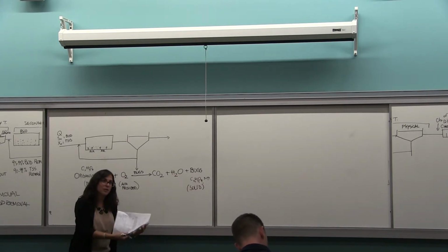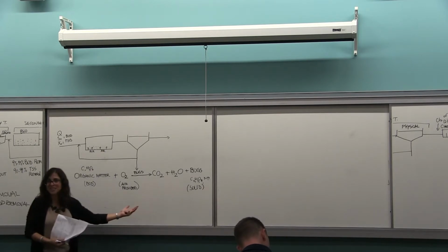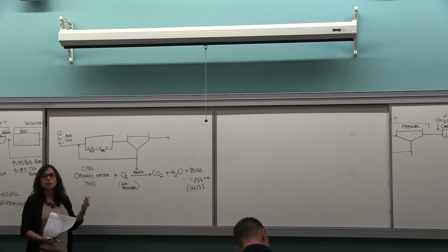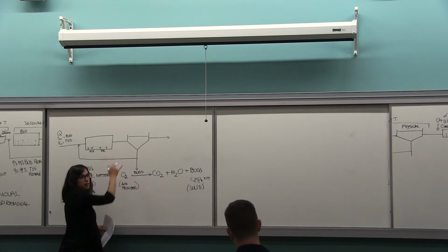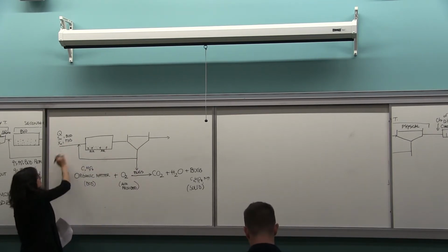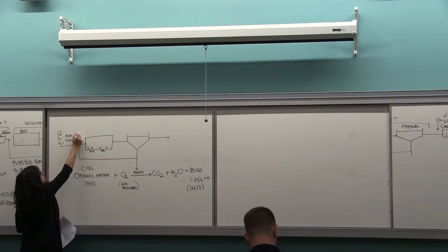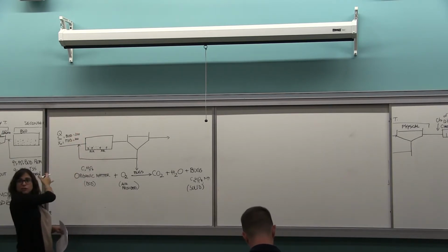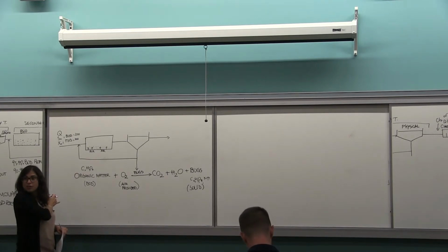Now, bacteria, we have a limit on solids, right? So we need to get rid of them. The clarifier removes the solids. So if X is the TSS, let's say we have 200, we have here 100 after that 50% removal in the primary clarifier.